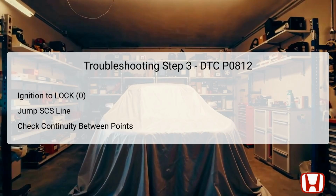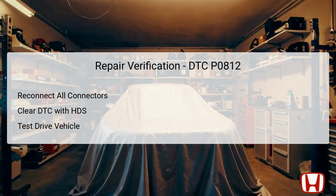After completing the appropriate repairs indicated by previous troubleshooting steps, it is critical to perform a repair verification process. Start by reconnecting all the connectors previously disconnected during troubleshooting, ensuring all connections are secure. Next, utilize the HDS to clear the diagnostic trouble codes, preparing the PCM for new data collection.